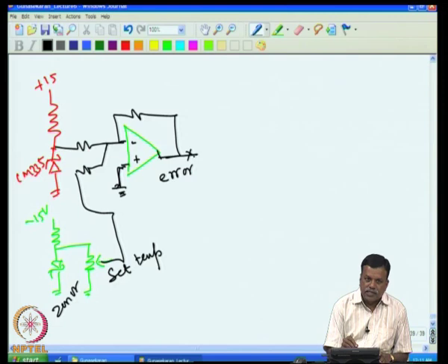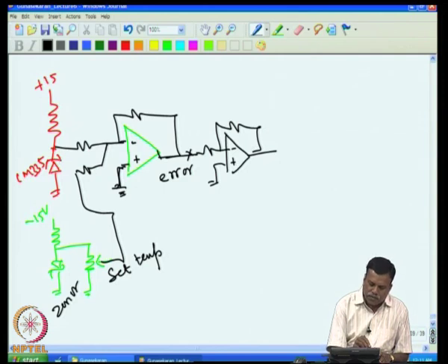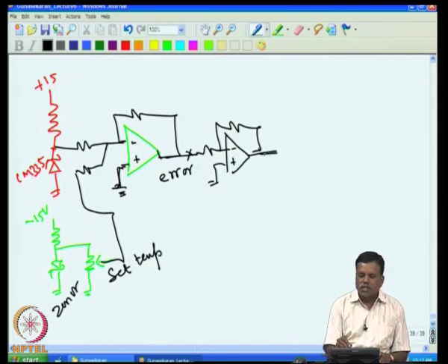minus side. So, when temperature increases, you will see that the minus voltage is increasing. If you actually want plus, we can also change it, or we can invert it, since it is an error voltage that we have to amplify and then add. So, if you want, we can invert it so that it becomes plus. Essentially, when temperature goes up, more plus voltage is coming here, and that makes this one go minus and this one go plus. So, when temperature goes up, essentially this voltage will be increasing.